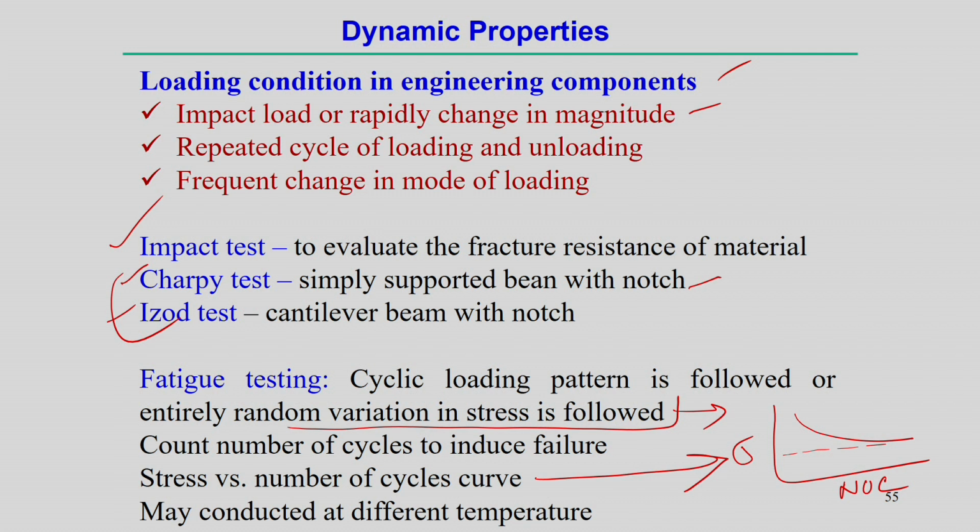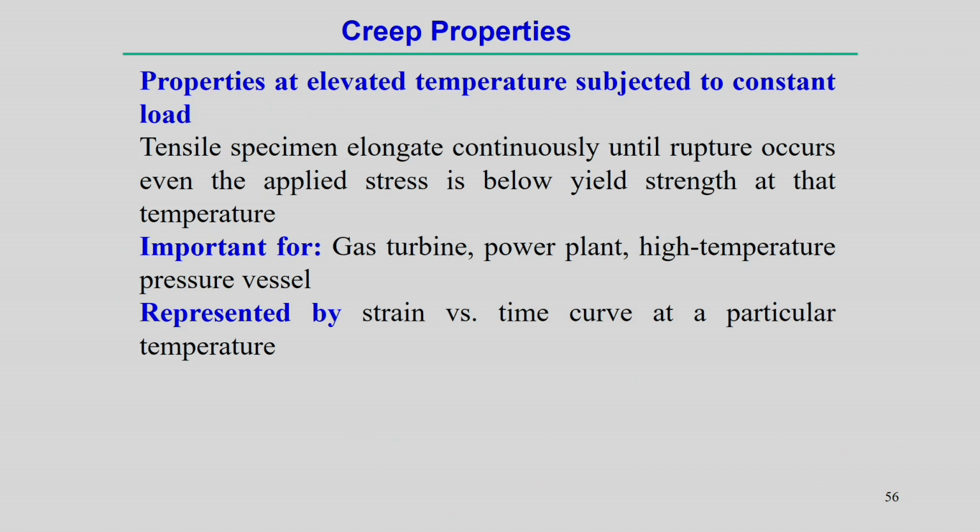So as a function of temperature we can conduct this fatigue testing also, and finally we will try to find out the number of cycles versus stress curve. Then apart from fatigue loading, there is another type of loading, that is the creep properties. We have already mentioned creep properties are simply properties at elevated temperature with the application of some kind of constant load, and how the material behaves in that situation.